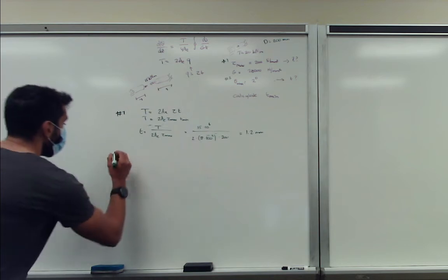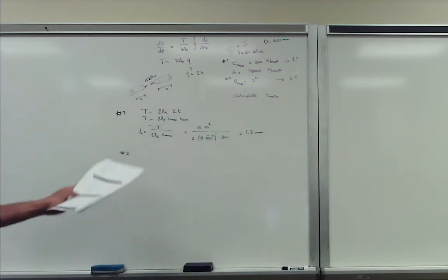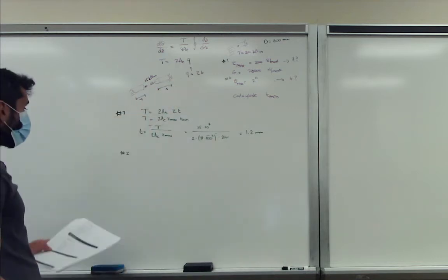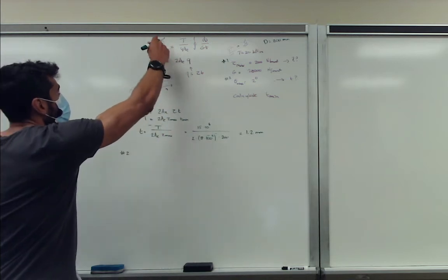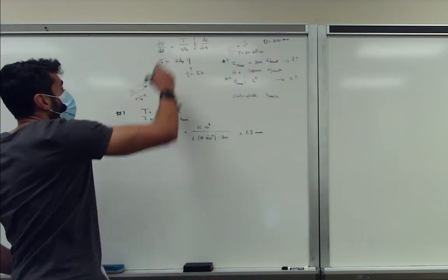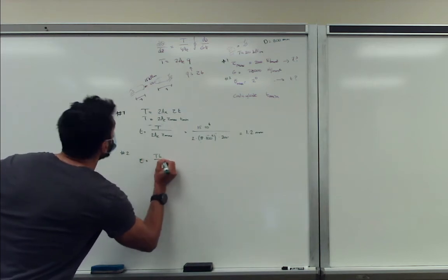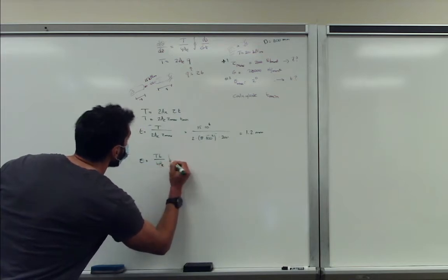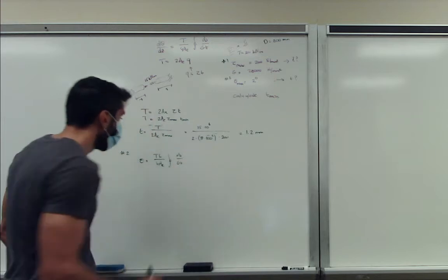So the second condition, let's check that as well. And that's the maximum angle. In this case, we apply the rate of twist. We integrate that with respect to z, so we add an L back to it. So we have theta is equal to TL over 4 times the area squared, times the integral of ds over Gt.